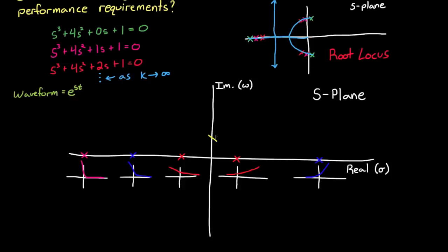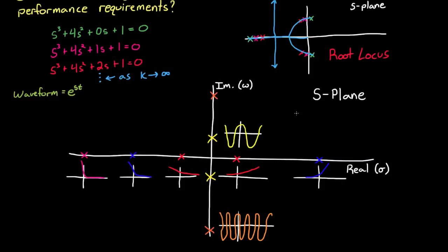The imaginary value corresponds to sinusoidal motion, or oscillations, in the time domain signal. These locations always come in pairs that are complex conjugates of each other. These pairs of complex conjugates are the results of dealing with real time. And the further the poles are from the real line, the faster the oscillations, or higher frequency. And a combination of real and imaginary values are a mix of the two, both exponential and sinusoidal motion.